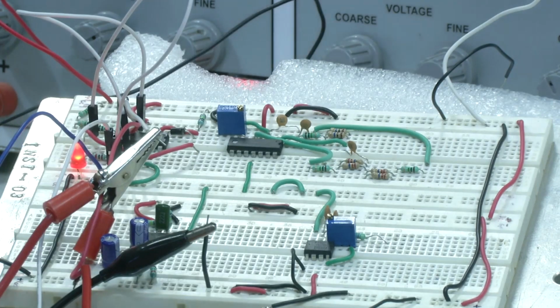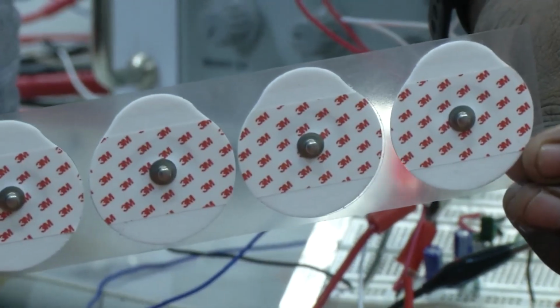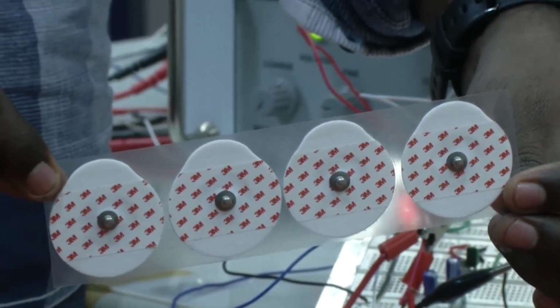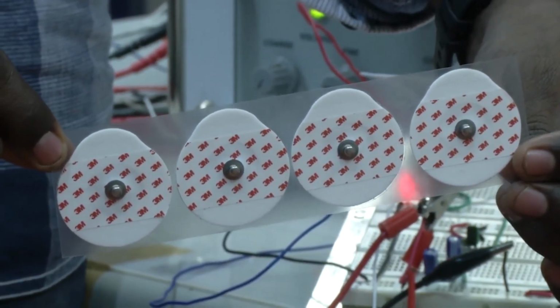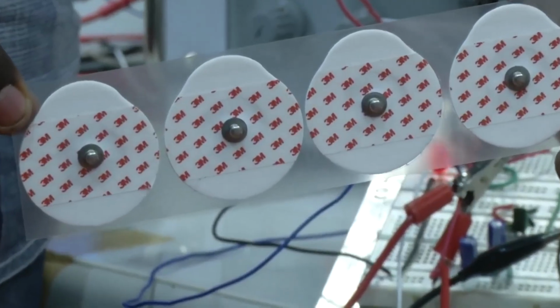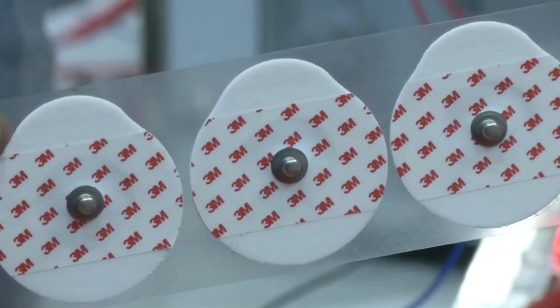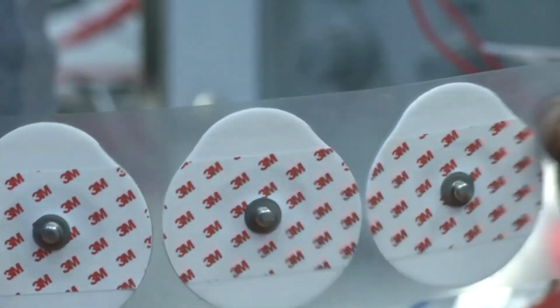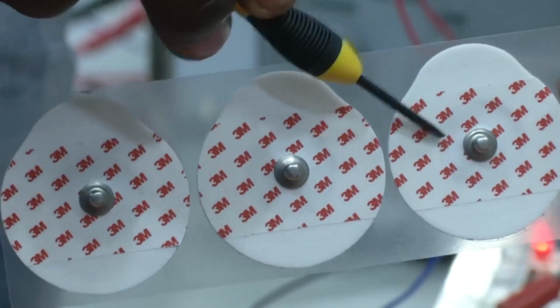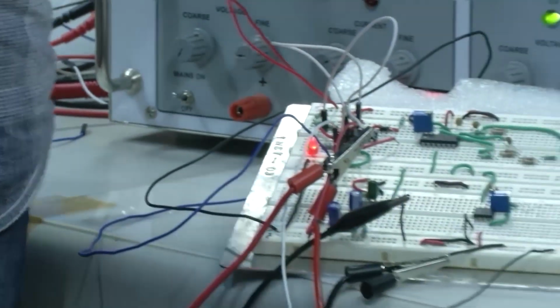Now, we have to take a subject, or connect a particular person, to the ECG electrodes. So, these are the ECG electrodes connected to the person. One at the right hand, another at the left hand, and the ground at the right leg, which we discussed at the start of our experiment. Here we will connect the electrodes to these metal pins, and we will see whether we are getting the ECG signal in the oscilloscope or not.